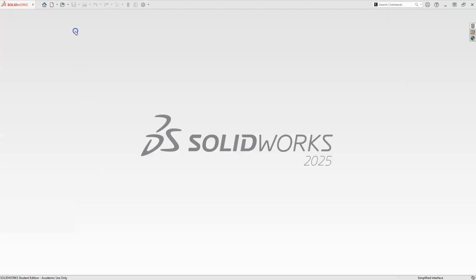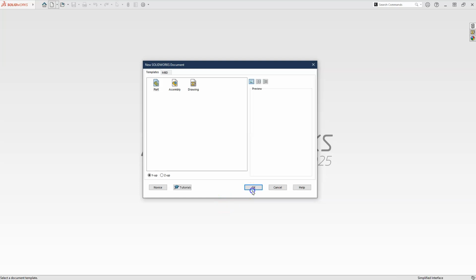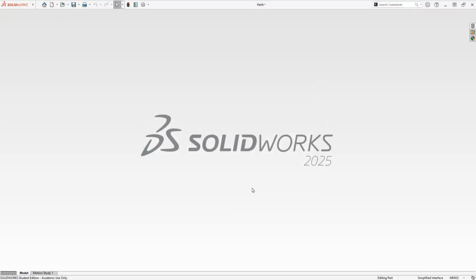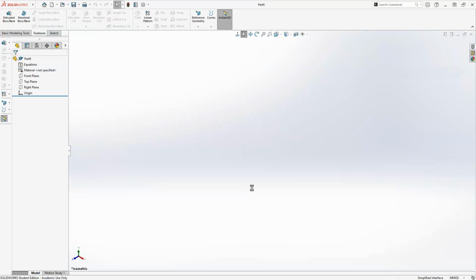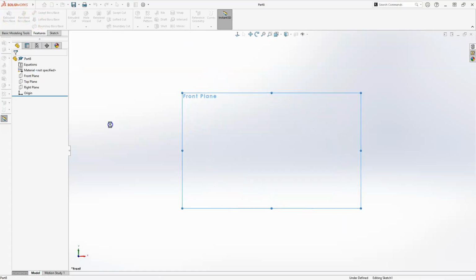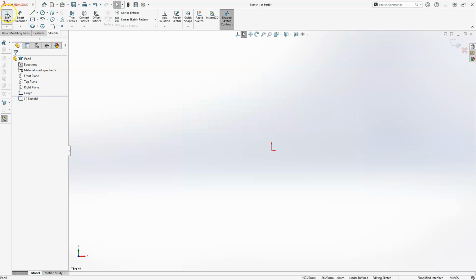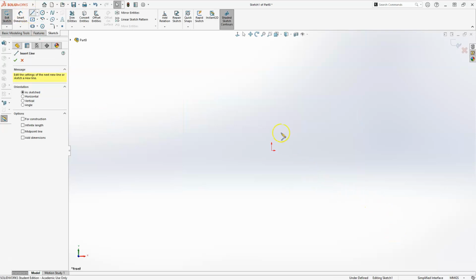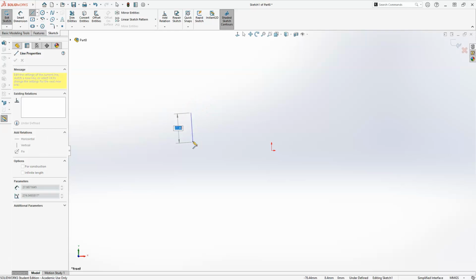Okay, so here in SolidWorks, I'm just going to start with the new icon here and hit OK. Now this is one of them that I can't do a thin feature with, so I have to create the actual profile. Let's look at the extrude command. Then I'm going to go to the front plane and sketch this out free-handedly. So I know it looks something like this.